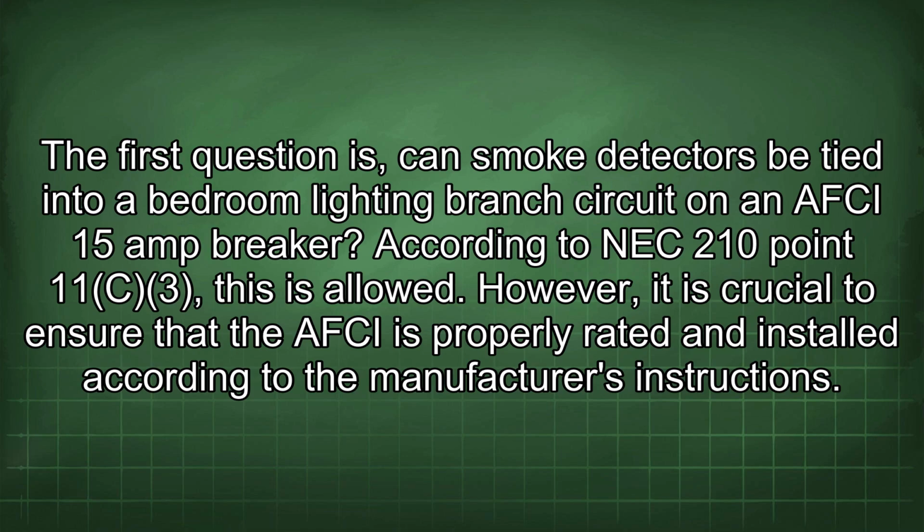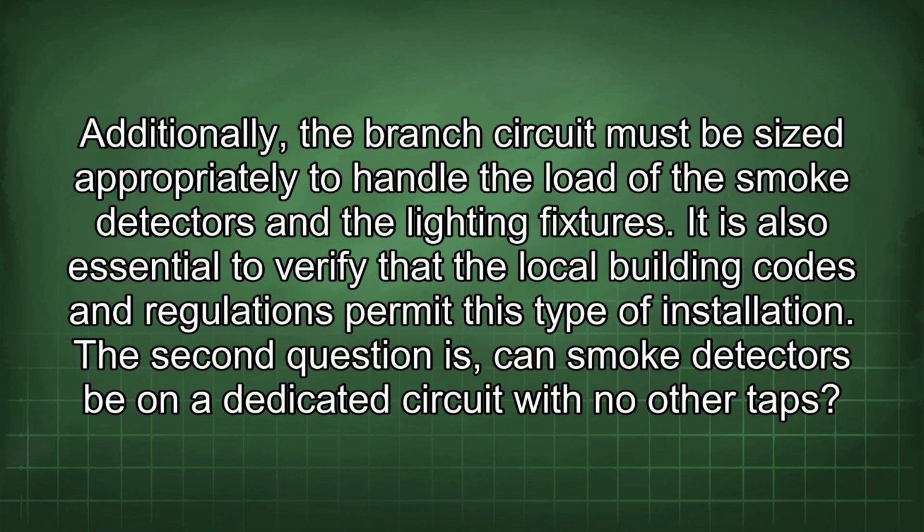The first question is, can smoke detectors be tied into a bedroom lighting branch circuit on an AFCI 15 amp breaker? According to NEC 210.11(c)(3), this is allowed. However, it is crucial to ensure that the AFCI is properly rated and installed according to the manufacturer's instructions. Additionally, the branch circuit must be sized appropriately to handle the load of the smoke detectors and the lighting fixtures. It is also essential to verify that the local building codes and regulations permit this type of installation.